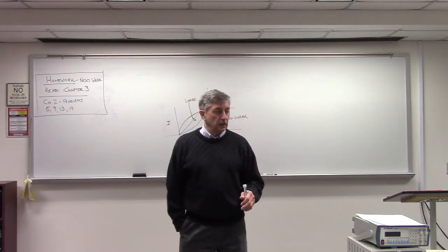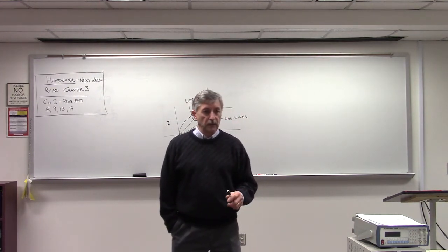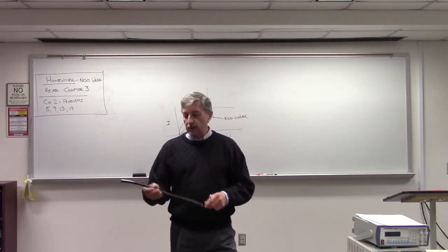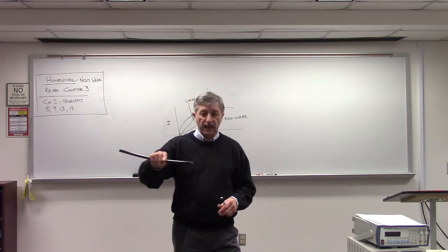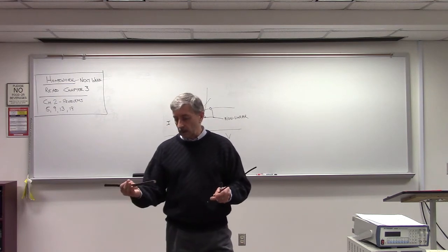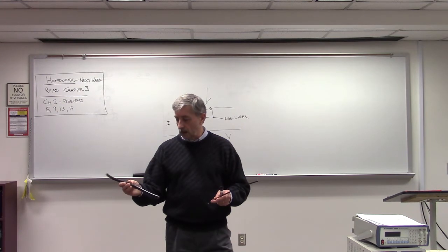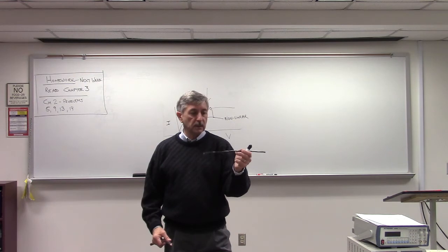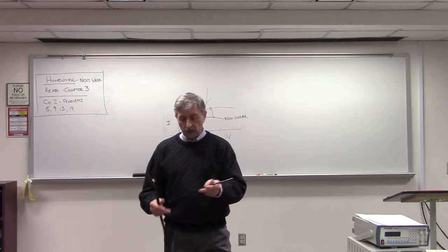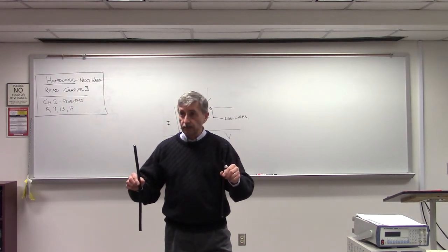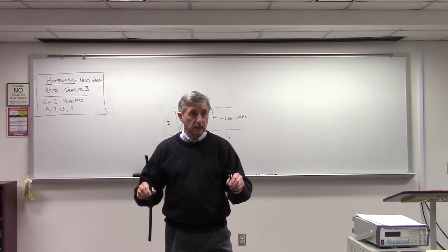So if you're looking at the resistivity of copper, and you want to calculate the resistivity, if you had a conductor that looked like that, or a conductor that looked like that, a little bit smaller. I think this is a size 2/0, I believe, a little bit bigger than this. This is number 6 wire. I probably should go over that, which I'll do. These would have different resistances, but the same resistivity.